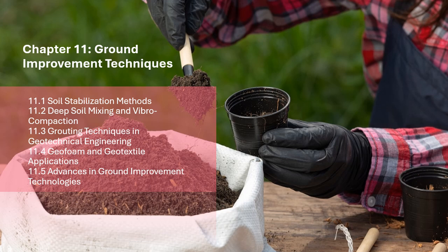1. Electrical resistivity heating. Electrical resistivity heating involves applying an electric current through soil to heat it. This method is used to modify the moisture content and stabilize soils in areas with problematic expansive clays. Purpose: the heat reduces the soil's volume changes and stabilizes its structure.